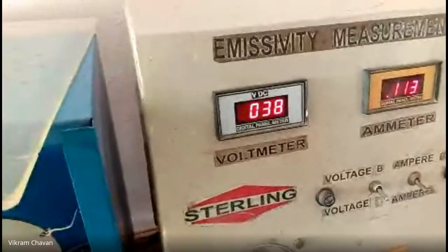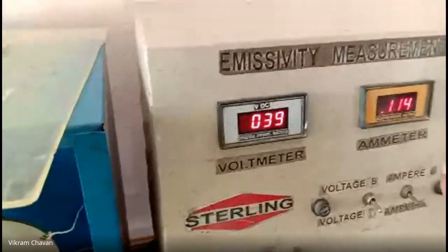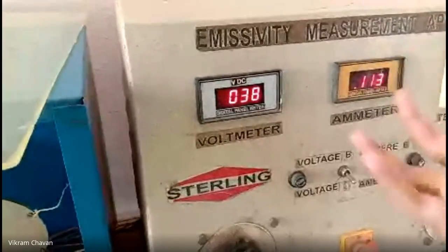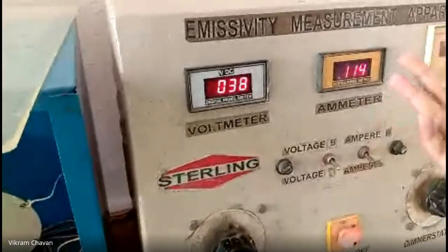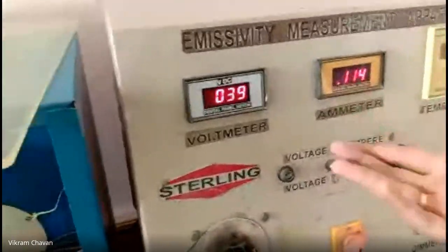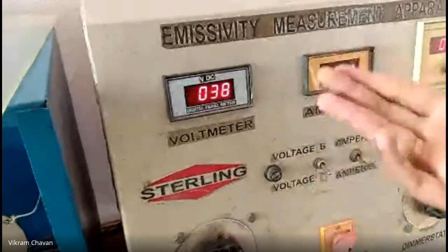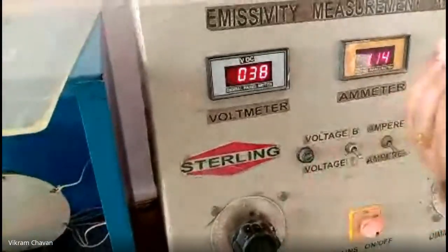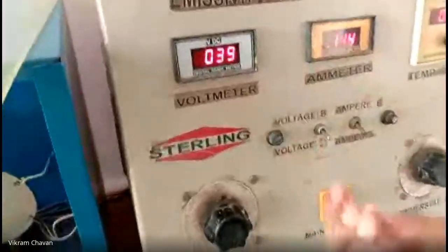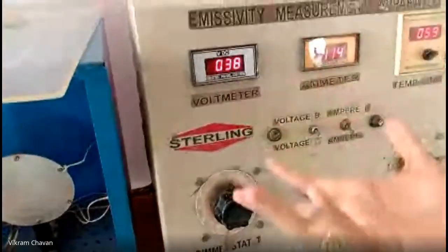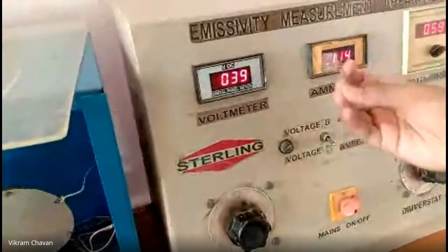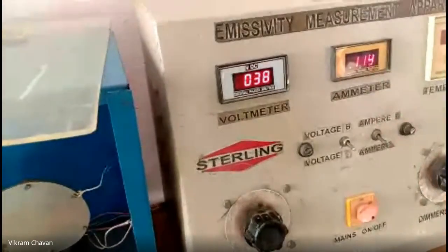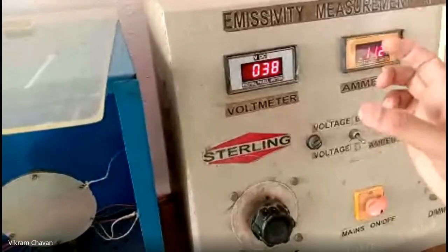Okay, so if you want to achieve the equilibrium state for both the plates, then for the test plate you have to provide less heat input as compared to the black plate. If you increase the heat input for the test plate, its temperature goes on increasing, because the emissivity of a black plate is high, and it will transfer heat to the gray plate also. And the gray plate is also generating heat. Because of these two combined, the temperature of the gray body will increase. So you have to use the trial and error method to achieve equilibrium between the two plates.